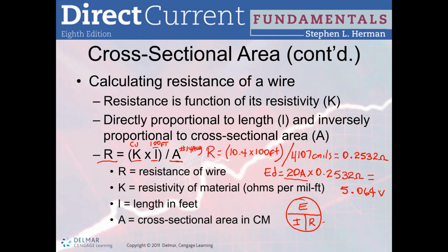Now I want you to notice that that's only the voltage drop that we experience in one of the conductors. If I have a branch circuit, and right here I have a switch, and that wire extends 100 foot from the panel or from the feeder to feed a motor, this is the hot conductor, which I call the hot just as a custom, or line one.